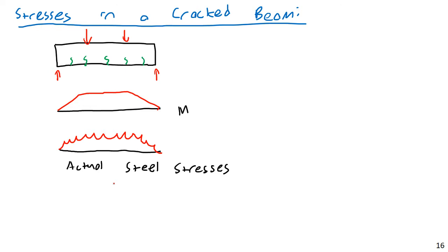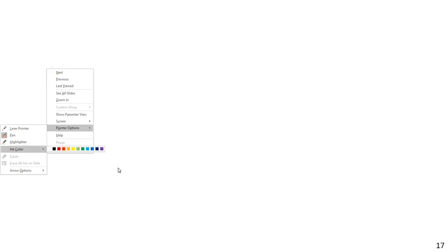That's one complication if we're looking at the bond strength needed to carry a required tension load. That's the actual stress that would be present, and it would need to figure into any calculation of development length. But not only do we have to worry about this stress in the steel, we also have to worry about splitting around bars.